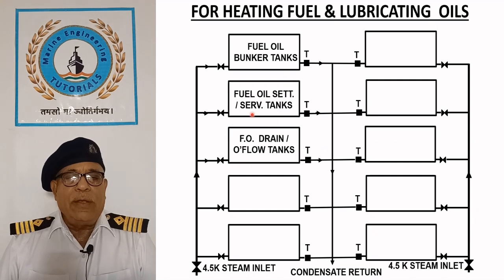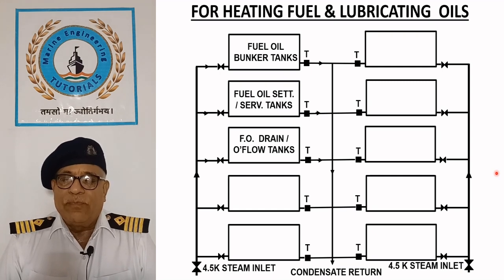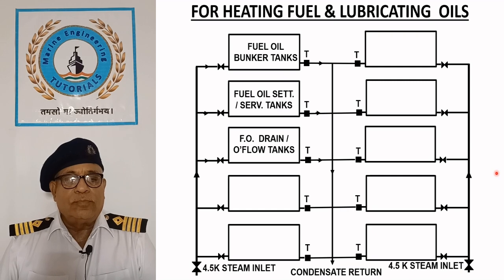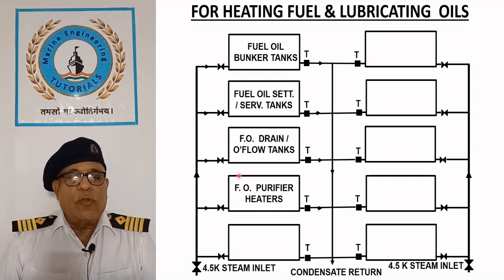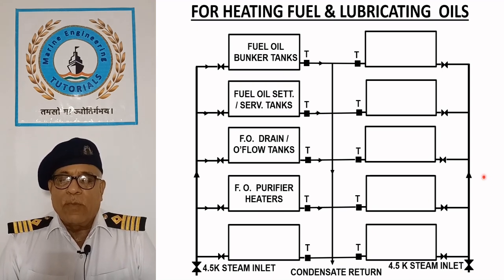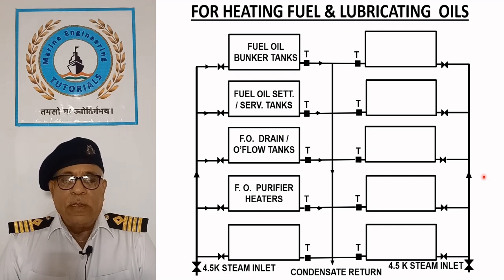Fuel oil drain and overflow tanks. Drain and overflow tanks, which may collect excess or drained fuel oil, are also kept heated to facilitate the transfer of oil back to the settling tank. Fuel oil purifier heaters. Before purification, heavy fuel oil is typically heated to around 98 degrees Celsius, which improves the separation of water from oil during centrifuging.